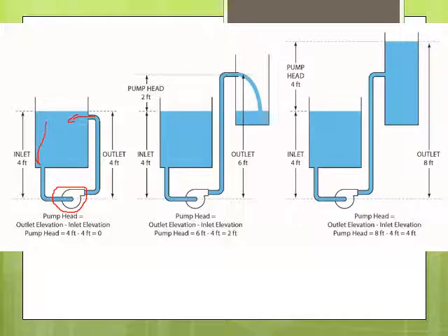Here we have a situation where the tank is above the pump, right? And we have a tank that is filling and the tank is still not full. So what is the ultimate head pressure? Well, we still have to go up to this high part. So that part here from here to here represents the difference, and that's our total head. Of course, as the tank begins to fill, it goes higher and our head increases. So when we're sizing pumps, we have to make sure we're looking at the extreme scenarios to make sure the pump will work in all conditions.